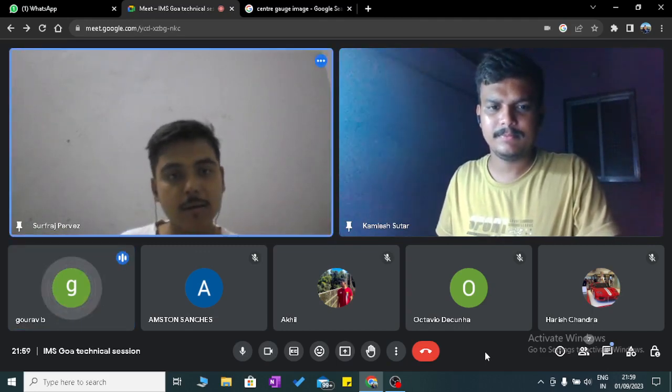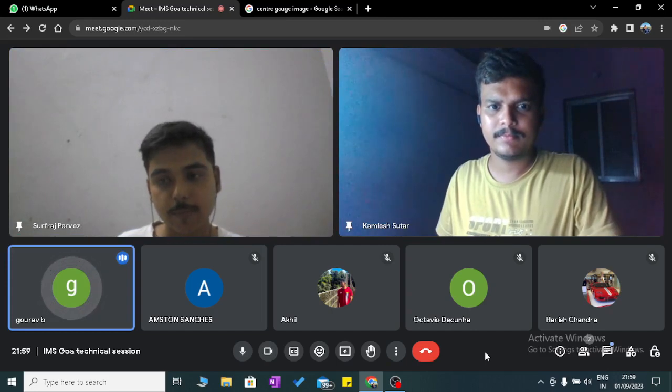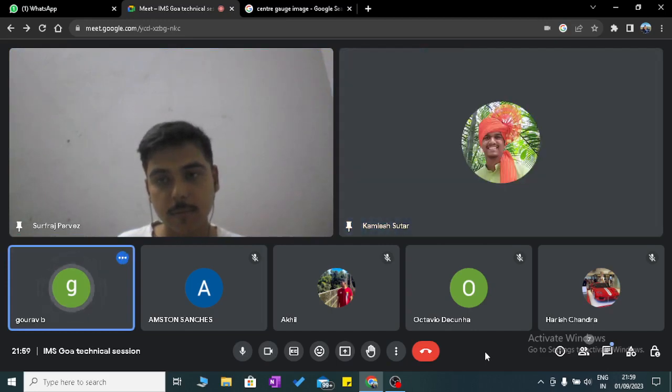Because the thread in between already has a gap, that is the thread teeth. Now, when we give a continuous feed, this thread teeth will not be created over here. That's why we require a gap distance between every thread, and this thread distance will always be created by the gear mechanism, which is predetermined by the company.